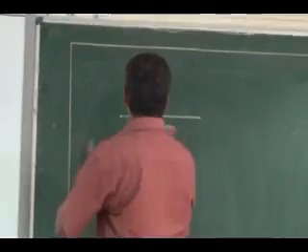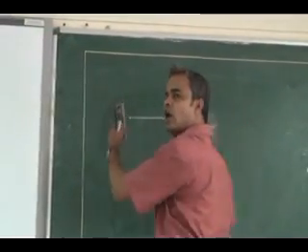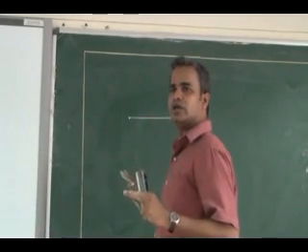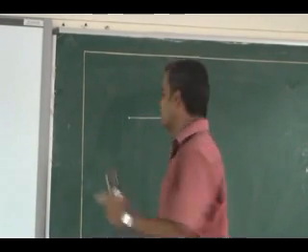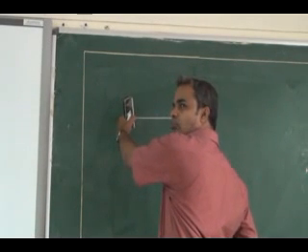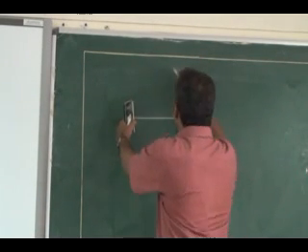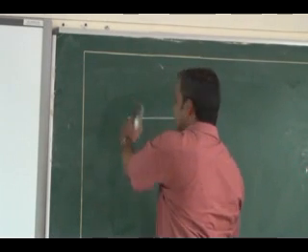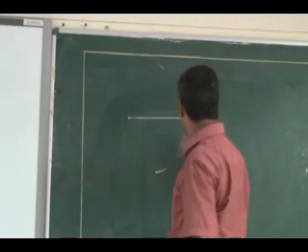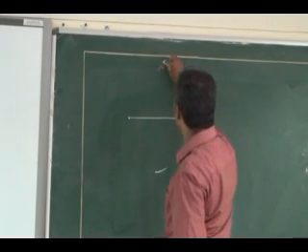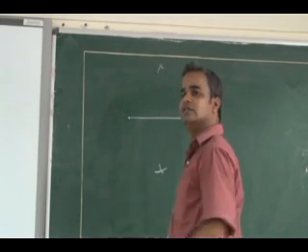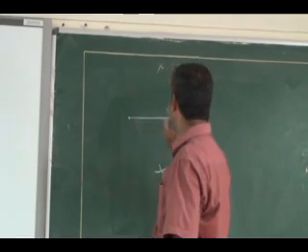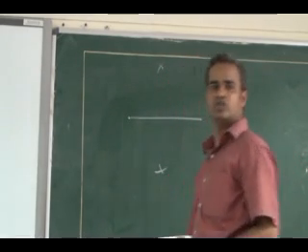Measure from this end. I can measure more than half the distance. I think all of you know this, right? So I can measure more than half the distance in my compass. I can cut an arc above the line and below the line, keeping the same distance from the other end. I can get an arc like this. Hence I can join these two lines, and that joining line will bisect the original line.